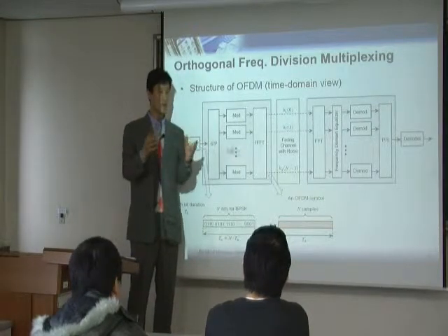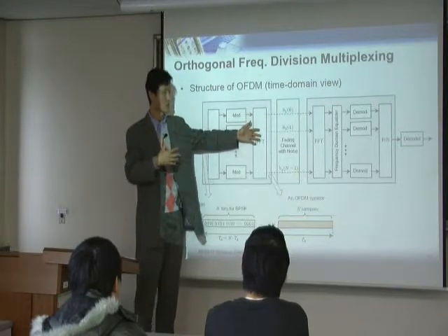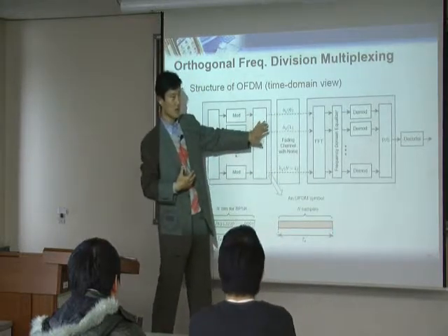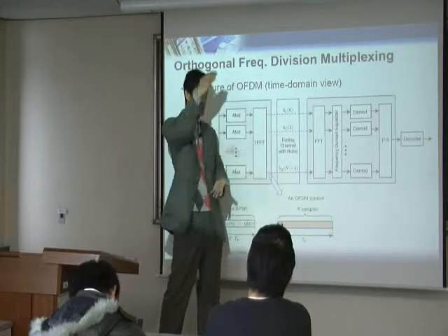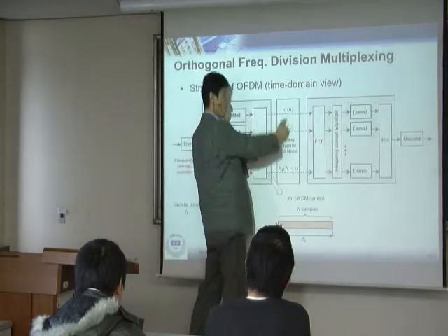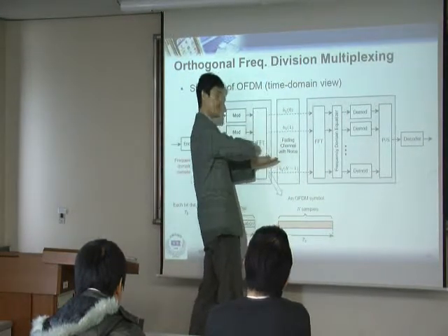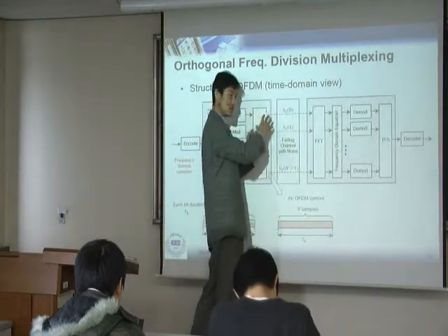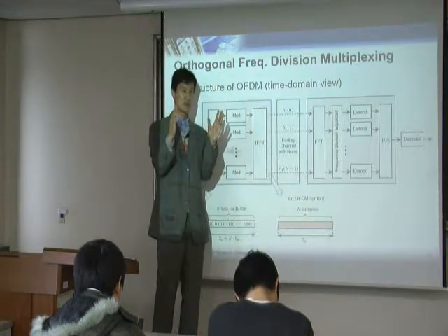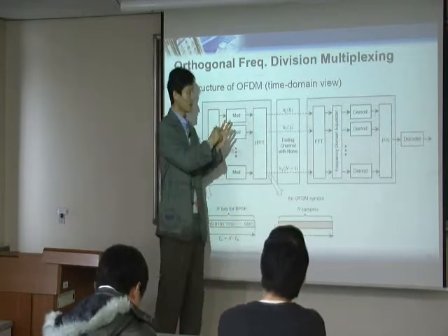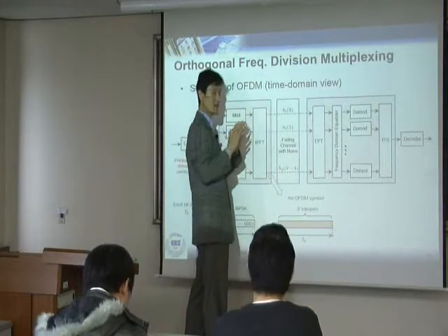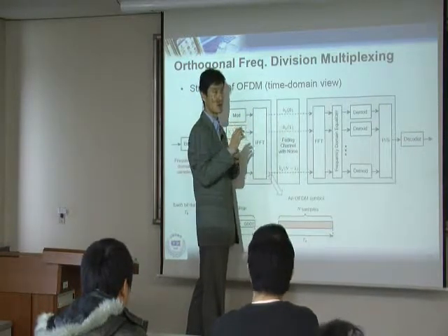So a power amplifier is simply an amplifier. You are amplifying your original signal, right? After this, we don't have that in the picture. Before this, all these things are baseband processing. Once you do that, the signal is amplified and then transmitted over the antenna. So if you have a very big sample and all the other samples are 0, and that signal goes into the power amplifier, the power amplifier always has some limited linear region. But suddenly, one of the samples is so big and the others are so low, then the power amplifier cannot amplify with the same gain.